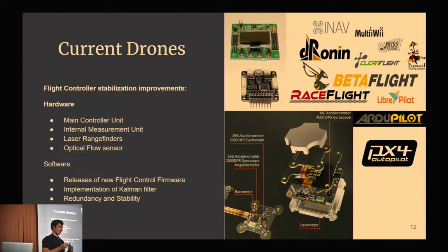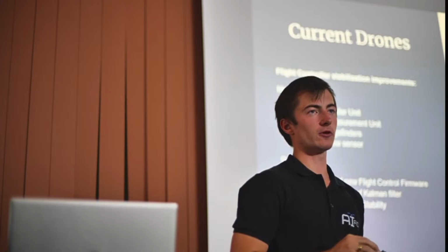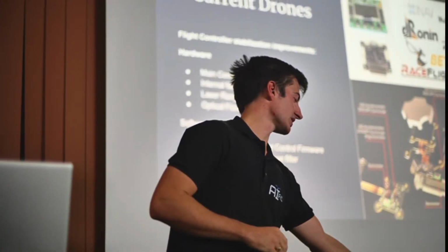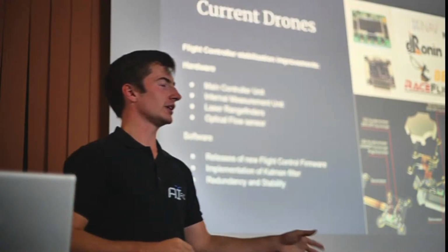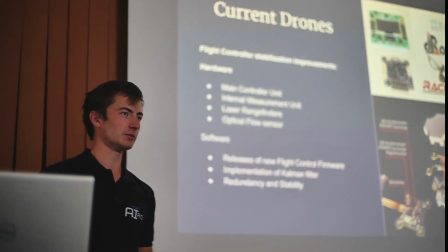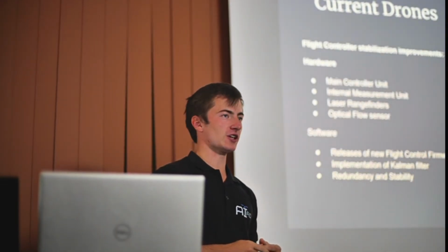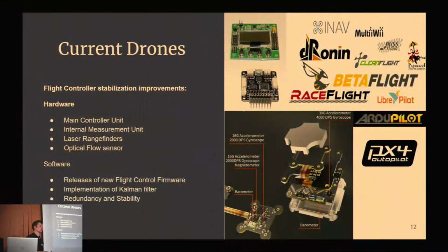And for example, there is an STM F4 flight MCU on board, and if we wanted to use, for example, an F1, it would be very hard to stabilize our little guy because of the low axis inertia, and he would crash very, very fast due to oscillations and lack of ability to track his rotational movement.